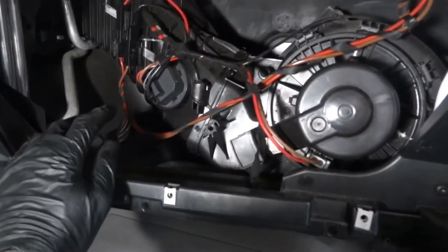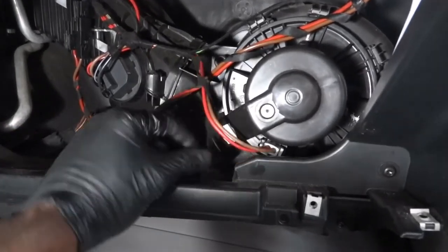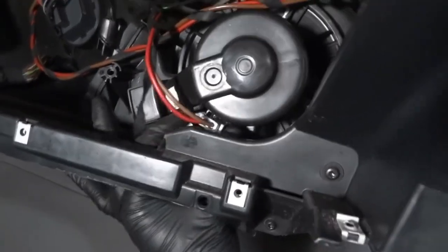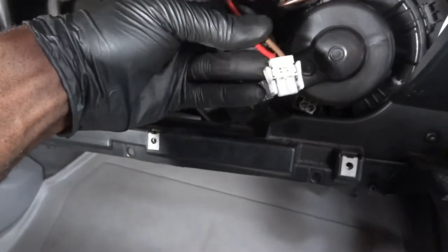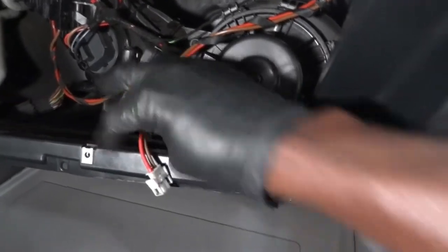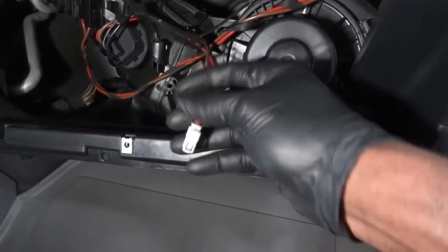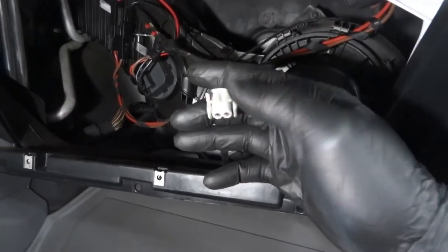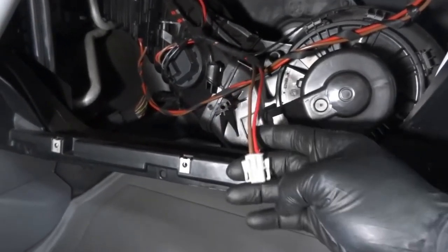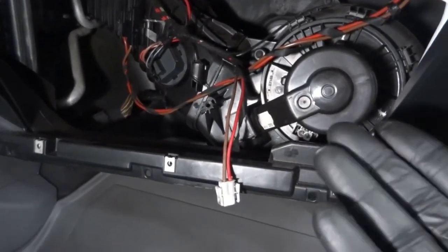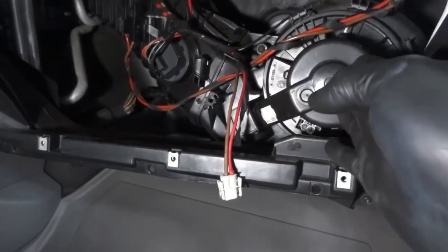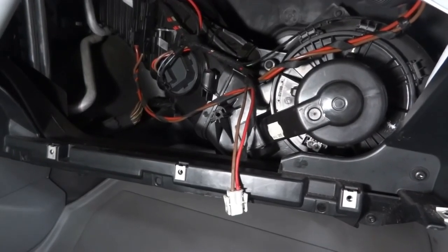So the first thing we're gonna do is, let's start by checking the blower motor itself. I'm gonna do that by disconnecting this blower motor electrical connector. So hopefully I can disconnect it while I'm holding the camera. Okay, right there. So here is the electrical connector to the blower motor. Okay, so what we're gonna do is, I'm gonna bypass the blower motor. I am going to connect a test light across these two wires. Okay, I'm gonna grab some piercing tools and then pierce these two wires. I'll connect a test light across these wires to see if our test light is gonna light. If our test light lights, then we can call for a new blower, because that would be the end of our diagnosis basically. Because if we have current flow or voltage at this point, then our blower motor should spin, right? So I'll grab the test light and I'll be right back.